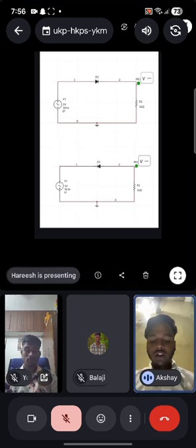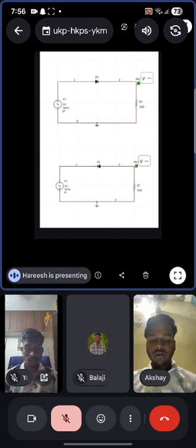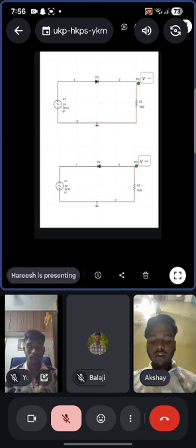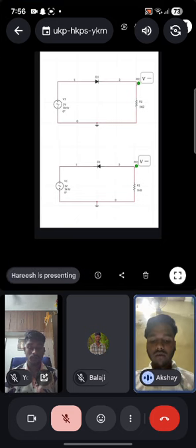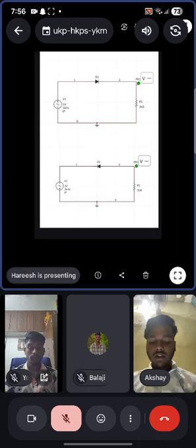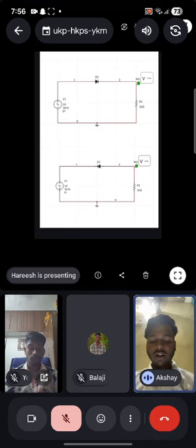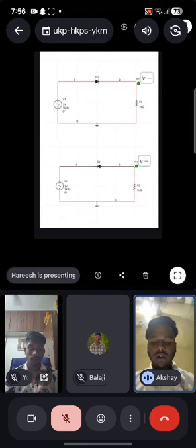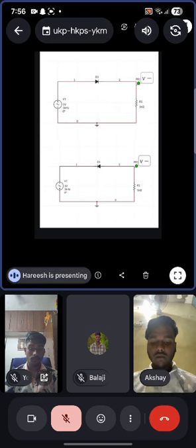In contrast, in reverse bias, we connect the positive terminal of the voltage supply to the cathode and the negative terminal to the anode. In reverse bias, the PN junction diode is described by the same diode equation as with a positive voltage applied. The total current is given where IS is the reverse saturation current, V is the reverse voltage, N is the ideality factor, and Vt is the thermal voltage.